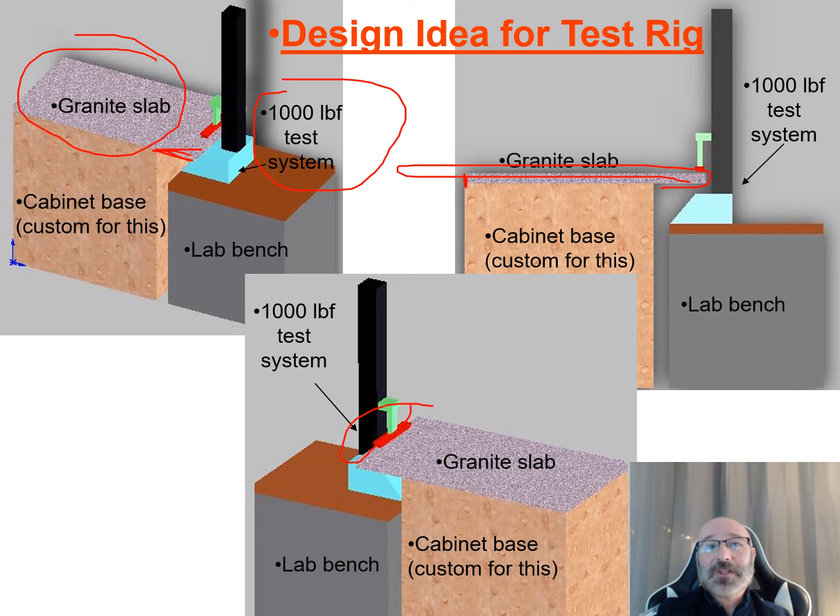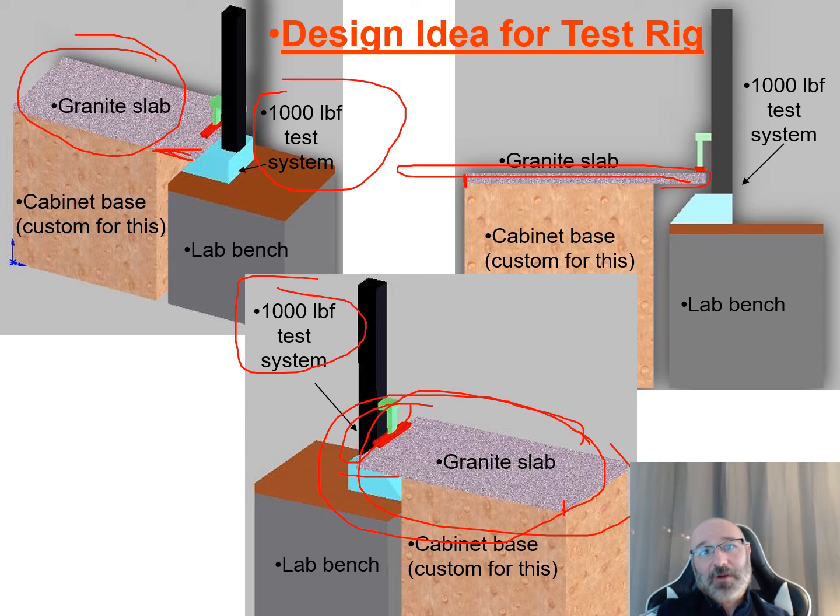on something like this. So even a simple project like this, you can specify the type of material, the dimension of the overhang, and the thickness of the granite, and then figure out, okay, for my criteria I need to go up to 1,000 pounds of static loading, will it handle it? And then again, that iterative design process: keep testing it. Well, no, 5 inches overhang was too much, or half an inch was too thin, or this material definitely didn't work. Let's try a different material.